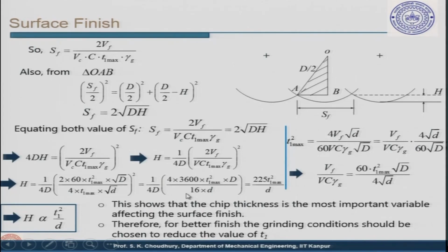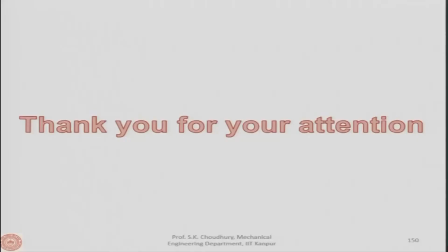So, here you can see that the surface finish of grinding is better than in the case of milling, which is better than in the case of turning, particularly for the sharp tool, and for the rounded-off tool the surface finish is better than for the sharp tool. So, this is what I wanted to tell you in the machining section, and I thank you for your attention. I will discuss the rest of the material in the course of production technology in the next discussion session. Thank you once again for your attention.